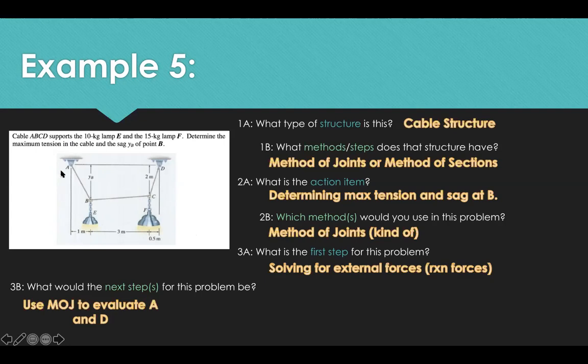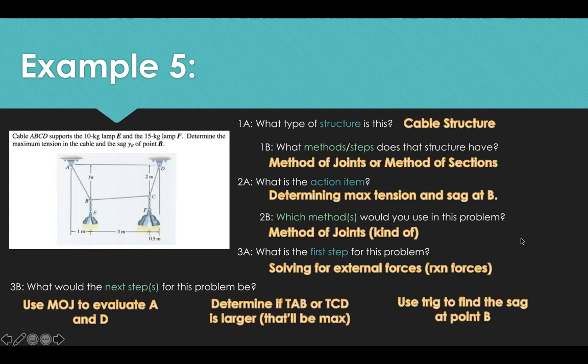No, so here you could do some of the forces, right? Because you know that this is just a component of that. So you know that the X component here would equal the X component at your reaction, and the Y component would equal the Y component at your reaction. Okay. So that helps you find what? So now that you know the components of this, what can you find? You can then find the YB by using those components as like a rise over run equation.